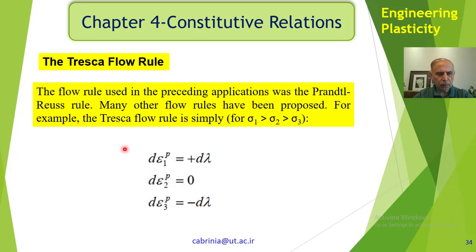Here I just want to show you another flow rule, as shown here. The flow rule used in the preceding application was the Prandtl-Reuss rule. Also we introduced the Levy-Mises, which is a special case of Prandtl-Reuss, and there are many other flow rules that have been proposed in many publications and have been used as constitutive relations.